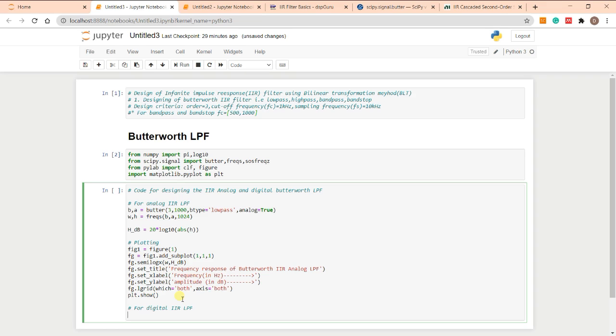as the name suggests that it's a digital filter, here we need sampling frequency, right? This is the basic thing. You people all have known this thing, right? So for that reason, I already mentioned that the sampling frequency that I'm going to take is 10 kilohertz. Okay, so with that parameter, I'm going to design the filter here. So let me first define the sampling frequency, because in digital filter we need that, right? So 10 to the power 4, yeah.